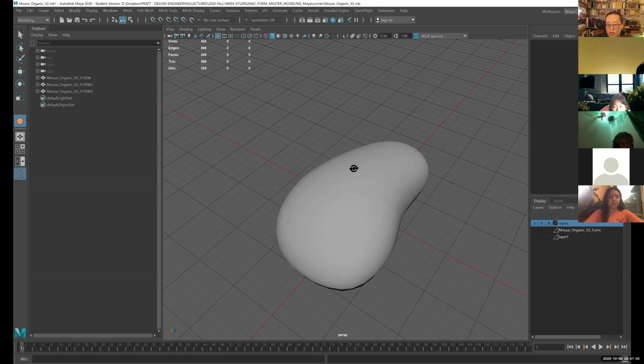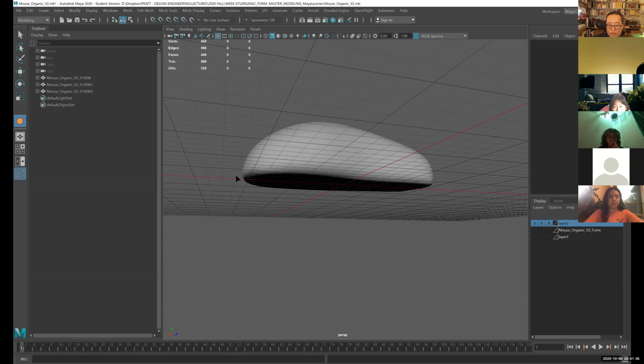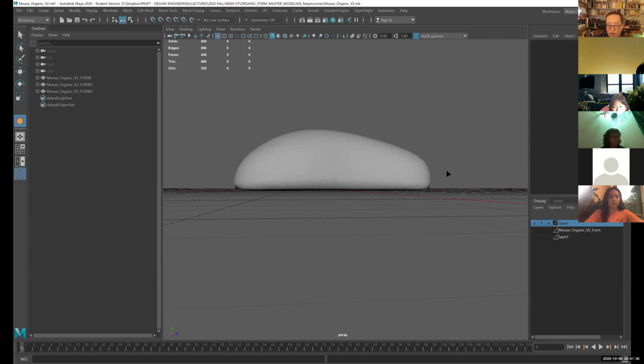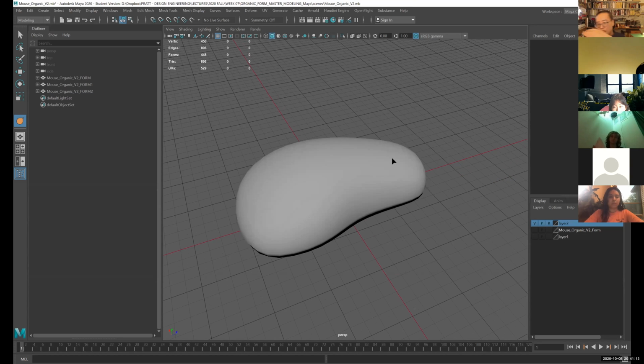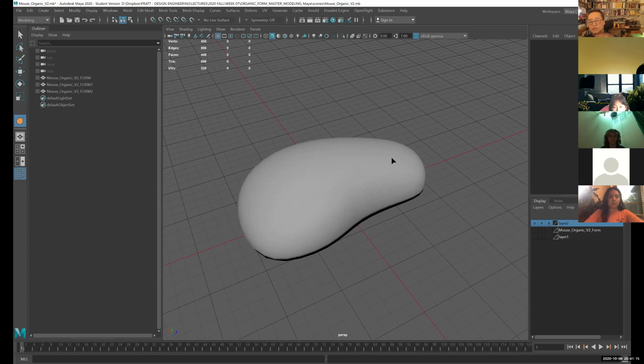So now what I'm going to do is create the surfaces that I'll be using for cutting purposes. This overall volume of form will be cut up into different pieces. Like the mouse product has a different shell, like the top and the bottom, and in this case, there's just a single slit for a button for a compliant movement. But many other kinds of mouse, like this one here, have divided, separated part break lines.